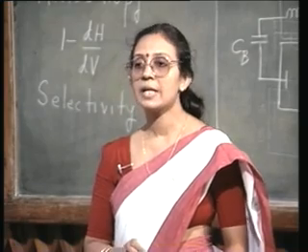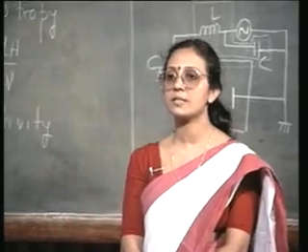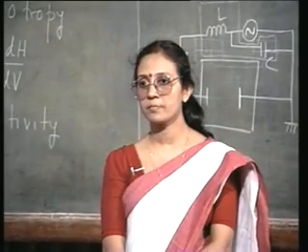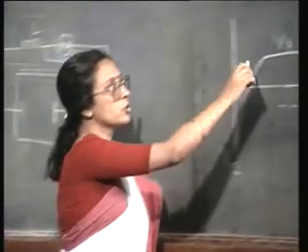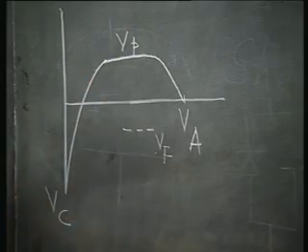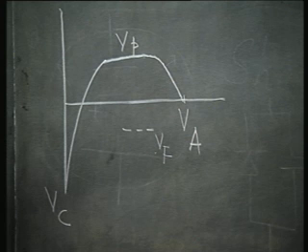If my substrates are placed on an insulating surface inside the plasma, the voltage difference is going to be Vp minus Vf, and Vf is negative. So, actually the magnitude of this potential is larger.